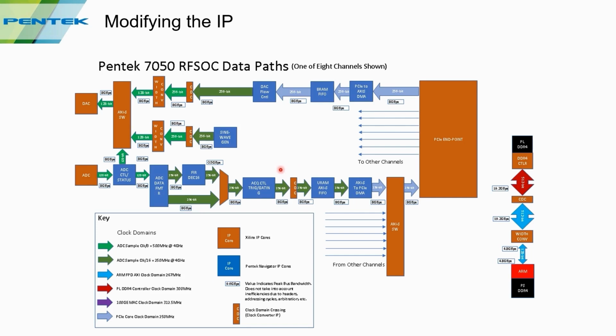And what this will allow me to do is monitor the traffic on a single channel. And I want to compare the single channel traffic with the PCIe traffic and see if there are any gaps in there or if there's any problem.